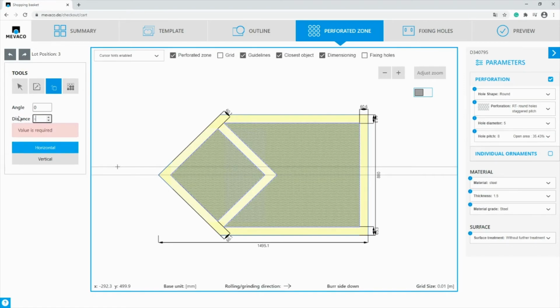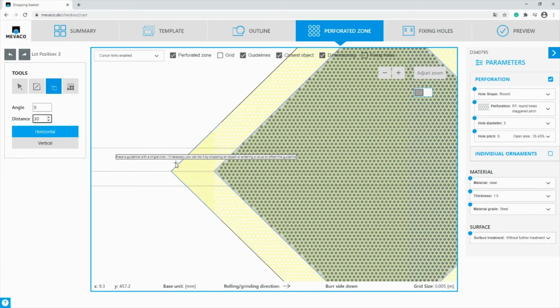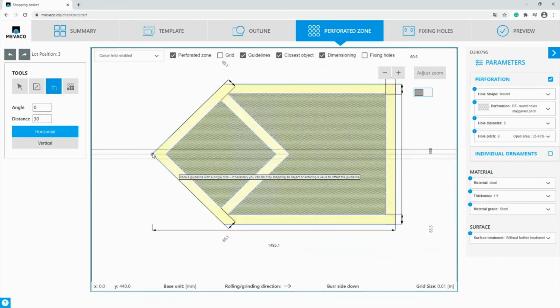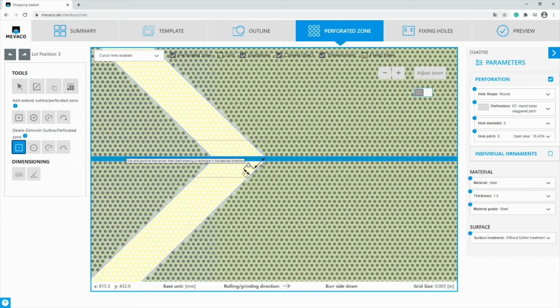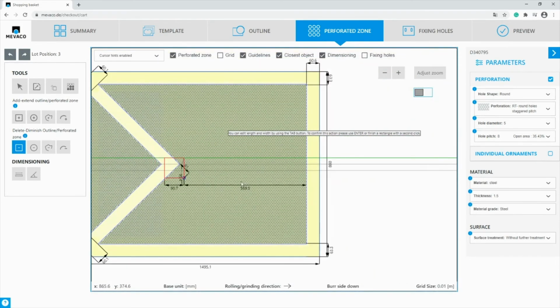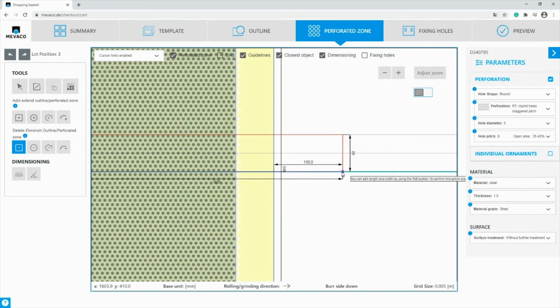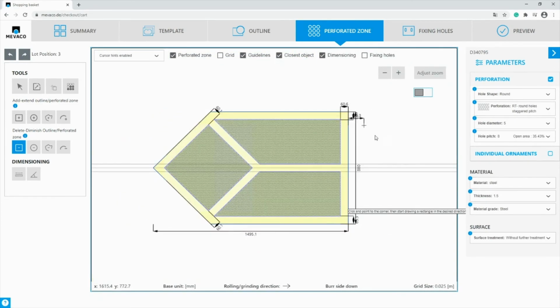And minus 30 and 30. And really I should be zooming in to see the point and place a guideline precisely. Here we go, we're almost there. So I'm gonna go to Cut Rectangular tool. This time I'm not using polyline, just simple rectangle, and do this really quickly. And you can go outside of your drawing, there is no harm in doing that. And click to confirm. We are ready.